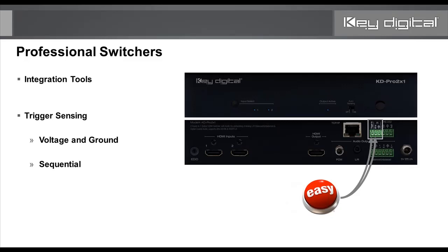And as often requested, sometimes you want to just have a simple button to control this. So you could mount an easy button here, or mount a doorbell, if you will. And on the Phoenix terminal, the main unit control, we have trigger input and ground. So just 2 wires in is all it takes. And with those 2 wires, you can press a button to sequentially advance from your current position, 1, 2, 3, or 4, and do that with a real simple interface for your client. Again, just making things as end user friendly as possible.